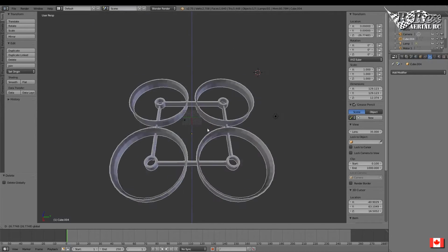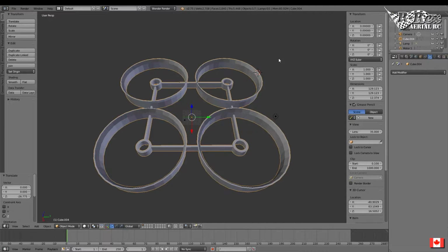So I can move it all around. It is one solid object. Now to test this, because whenever you print something, I'm sure you've probably downloaded things from Thingiverse and they've come up and said that they're not manifold. Basically manifold means that the object is solid and that there are no holes or overlaps or things inside of the object, so that if you were to fill the inside of the object up with water, it wouldn't spring a leak somewhere. So to do that, there is actually a feature inside of here to test for manifold.